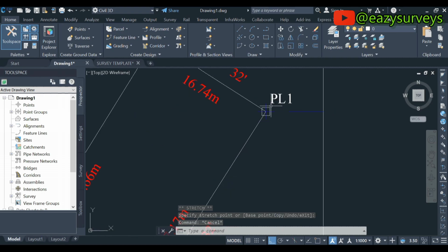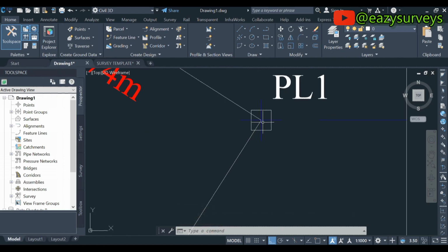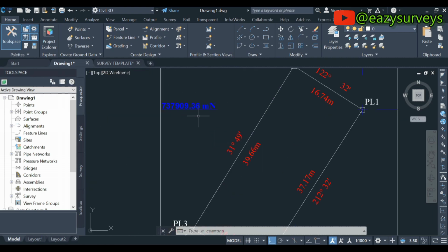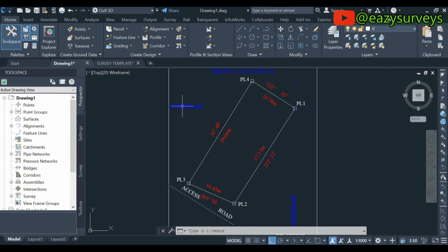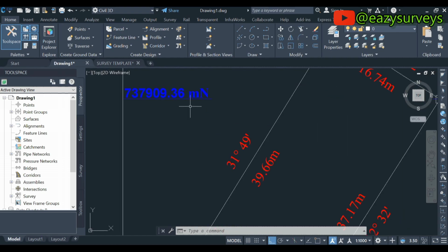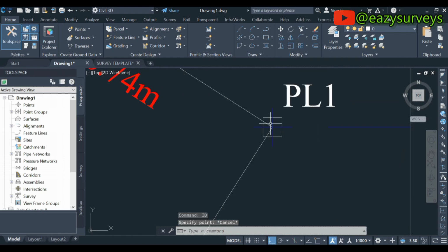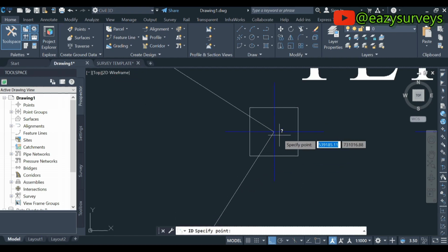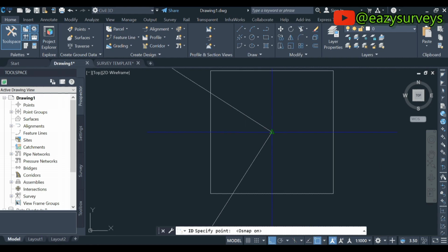And lastly, you have to edit the coordinate of the origin point. So this is not the real origin coordinates. Then to bring out the coordinates of this origin pillar 1, alright, you come to the command line, then you can activate your whole snap this time around. Then you come to your command line, then you type ID, then you click on enter. So you have the advantage to choose the center of this. So let me activate the whole snap to accurately pinpoint the center.